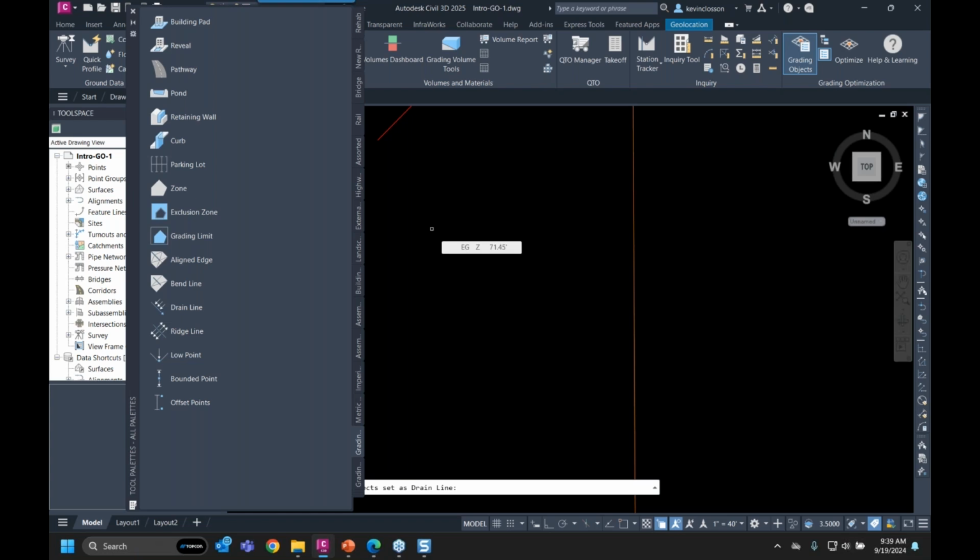And then when that information comes back to you, if you don't like it, or it's too tight, or it's pulling weird triangles in some direction, or whatever it might be, that's where that iteration process comes back in. You would go back into each one of these little properties here and say, let's change that a little bit, or give minimum, maximum elevations to a retaining wall, or whatever it is. So that's a big part of it.